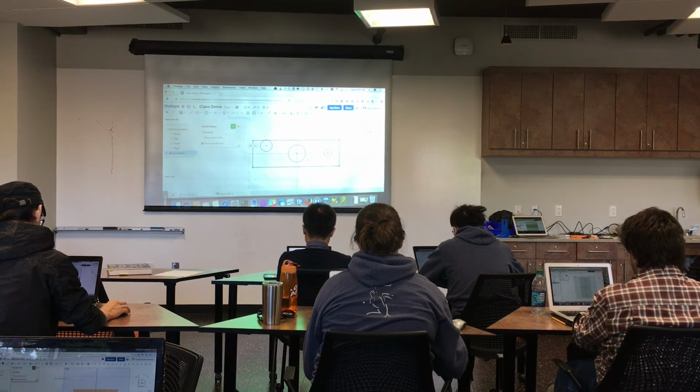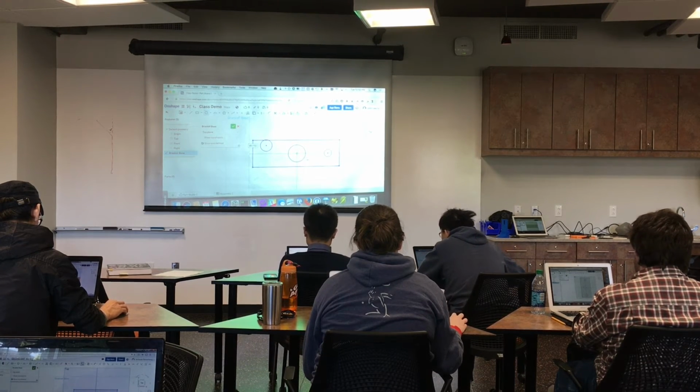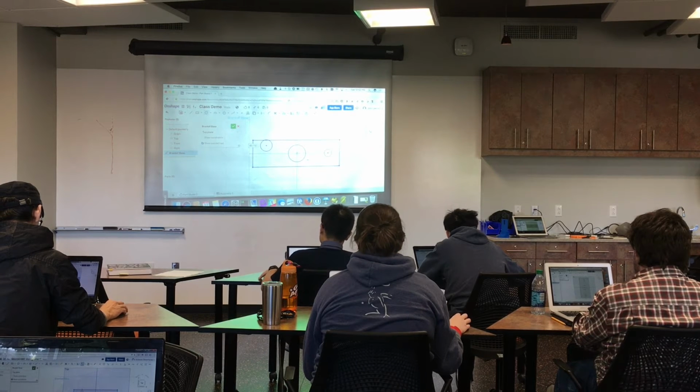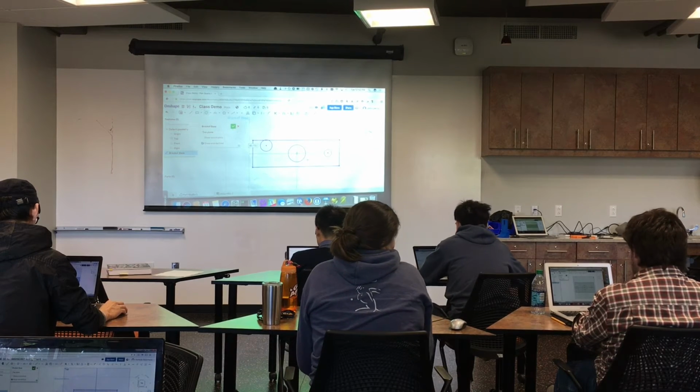And this is way easier than it was even a few years ago. So it's awesome. Is there a way to just take one piece and then, like control C, control V it? No. So if I wanted another piece of identical diameter size, I need to draw that out to the same size again. We'll constrain it in a second. So we'll use constraints to do all the sizing.